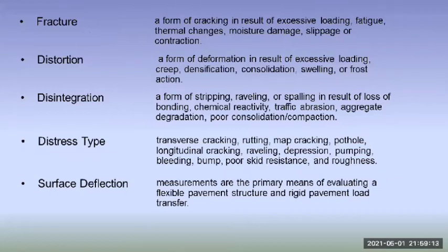Fracture, a form of cracking as a result of excessive loading, fatigue, thermal changes, moisture damage, slippage, or contraction. Next is distortion, a form of deformation as a result of excessive loading, creep, densification, consolidation, swelling, or frost action.